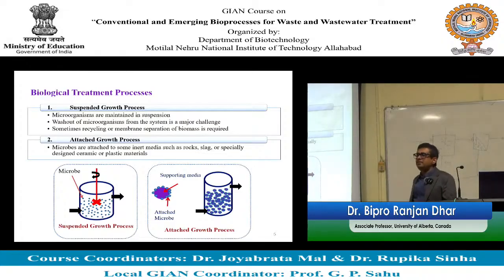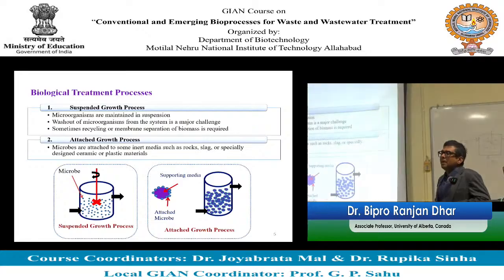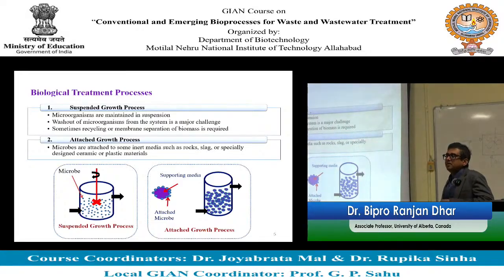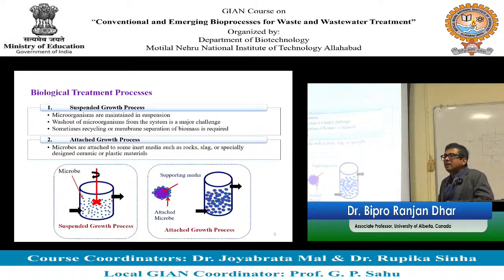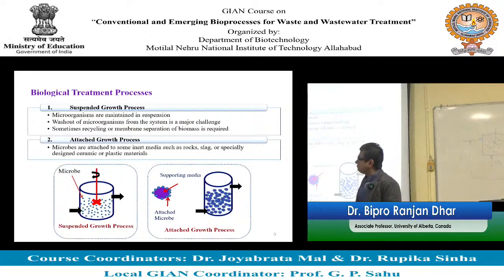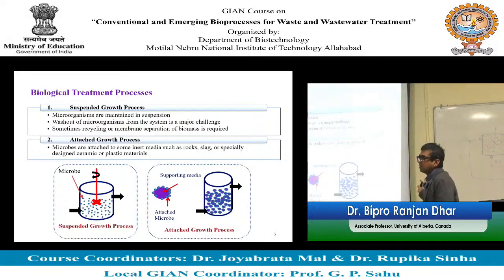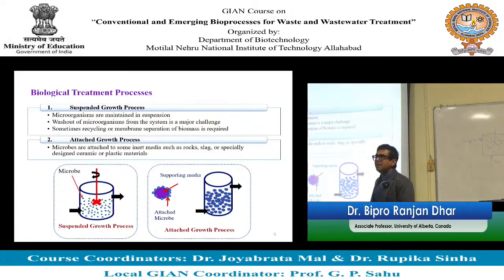Yes, there are many different configurations of MBR, but MBR is not very typical because the maintenance and capital investment for membrane is really high. So sometimes it's a deal breaker for municipalities because they want to reduce the operating cost, right. So typically membrane is not widely used, okay. But maybe for some industrial wastewater, yes, that might be an option, okay.